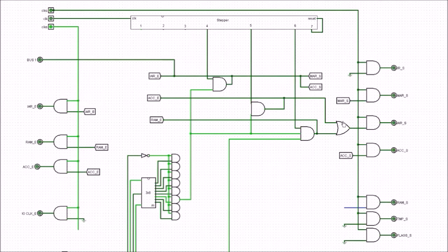So that means that the feed in from this OR gate won't come from this point here. It's going to come from this point here, which is the next address of the RAM, which contains the address that you're actually wanting to jump to. So in that instance, what goes on to the instruction address register isn't the value from the accumulator, it's going to be the value that's in the RAM, which is the next address in the RAM.